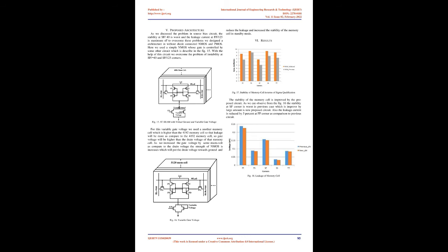In a dual power supply SRAM, we use two power supplies, one for the memory array and the second for the peripheral. In SRAM most of the leakage power, static power and dynamic power is dissipated by the peripheral of the SRAM, so for low power consumption the peripheral is put at a lower voltage compared to the memory array voltage. The word line selector and row decoder are also put on the memory array voltage because the row decoder drives the word line of the memory array. As shown in the figure, the power supply of the memory is VDDMA and the power supply of the peripheral is VDDMP. For less power consumption, the peripheral power supply is less than the power supply of the memory array, VDDMP < VDDMA.